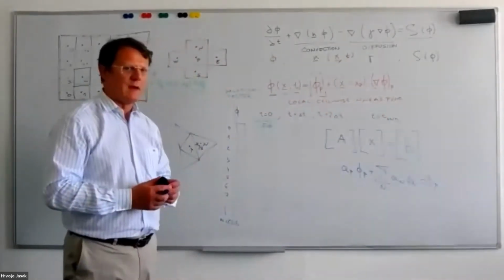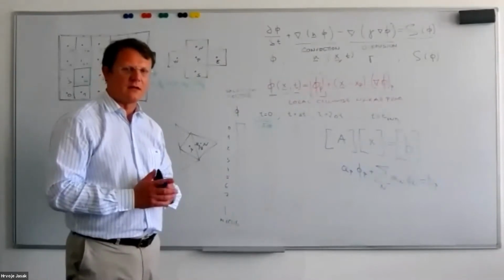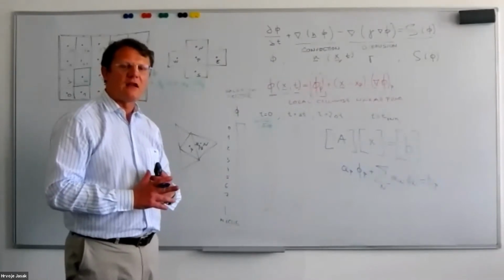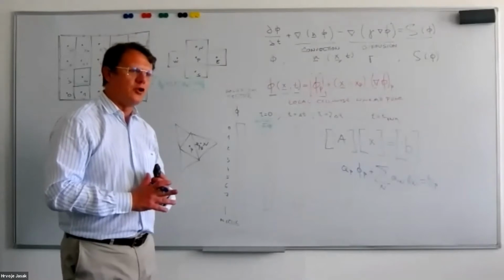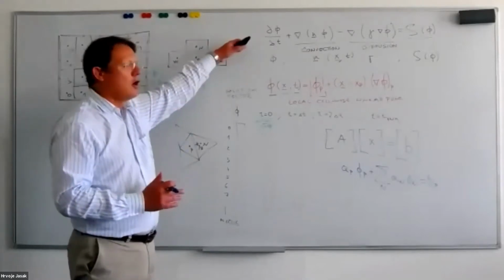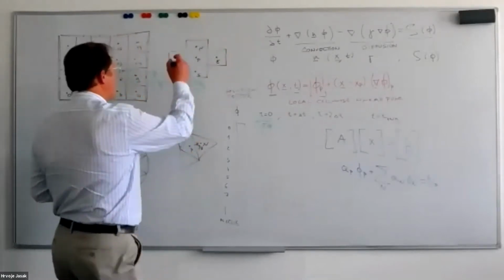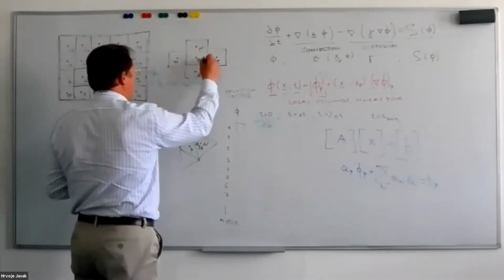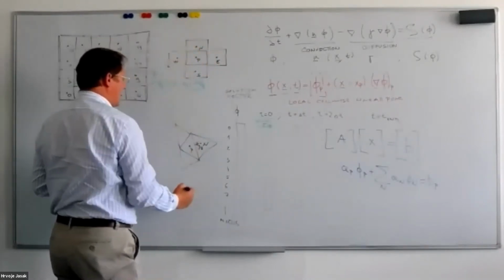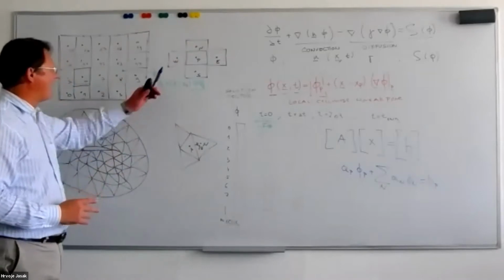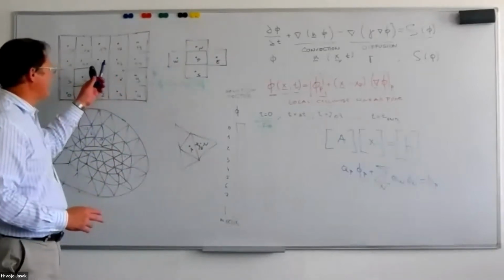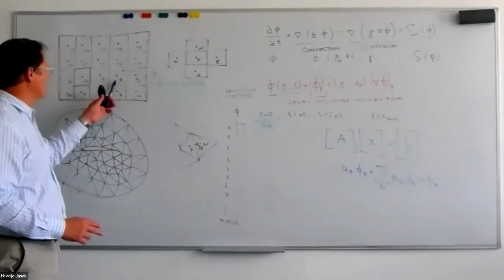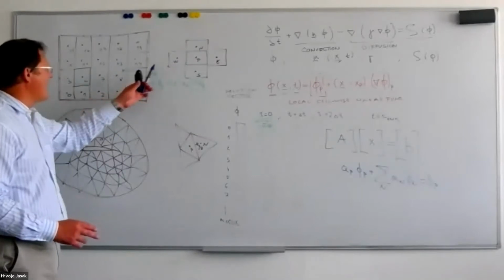The finite volume method will perform this discretization by calculating the volume and surface integrals of my equation over the chosen control volume. Here behind my hand, I have two representative shapes of a control volume, say for my volume 8.